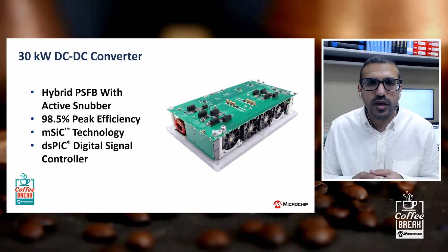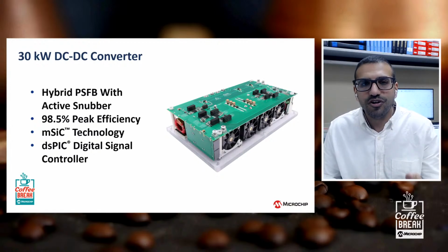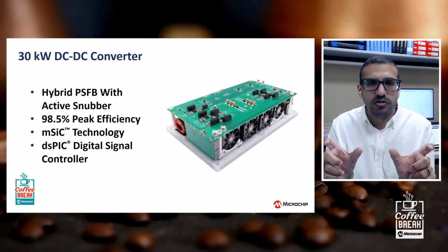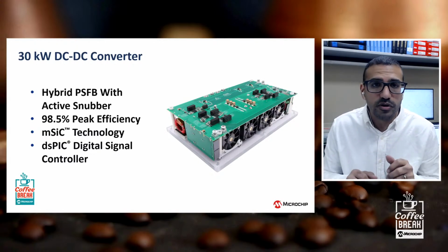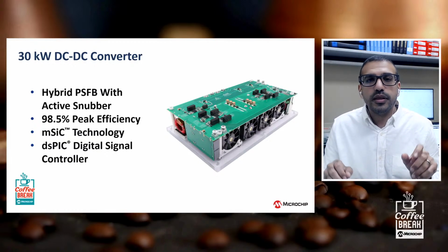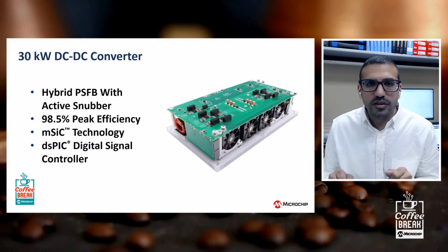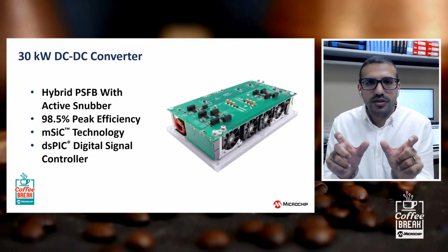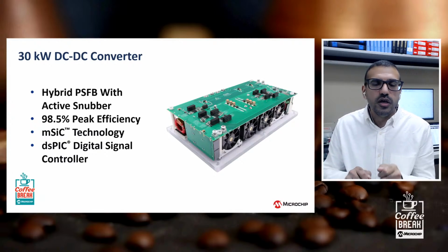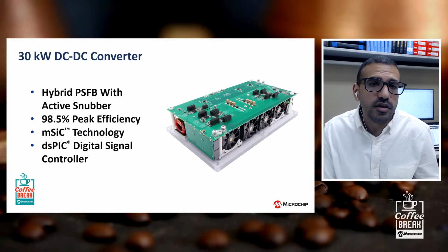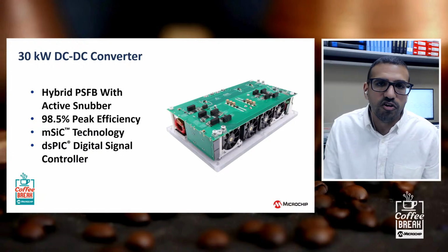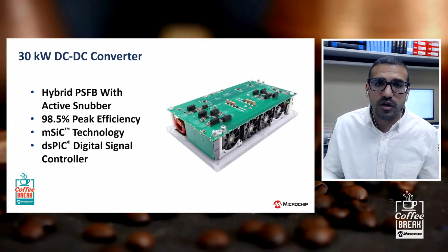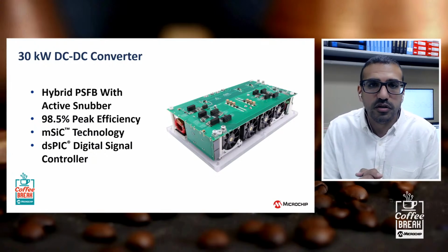The way it was designed is that it's a phase shifted full bridge, but there's actually two of them. We have these two H bridges that are operating, each at a duty cycle of 50% and 180 degrees phase shift, okay? Now, there's only one control variable, though, and that's the phase shift between these two H bridges. So that one variable is all you need to control the output. This converter takes in the 700 volt output of that PFC and outputs a voltage range between 150 to 650 volts. And that's a very wide output voltage range, especially for an isolated DC-DC converter.